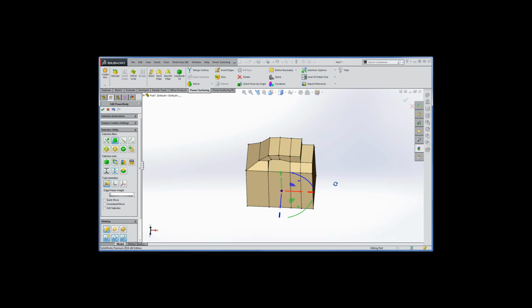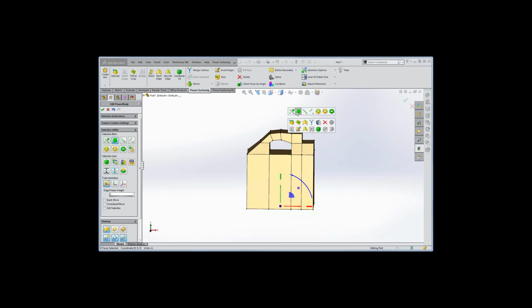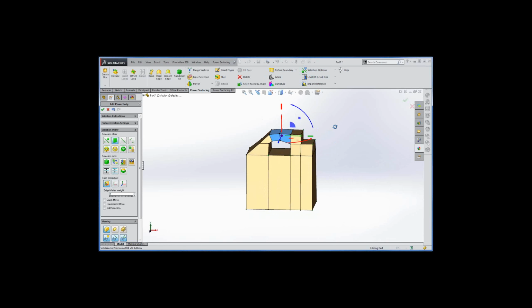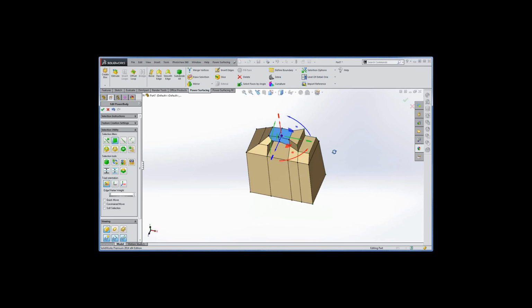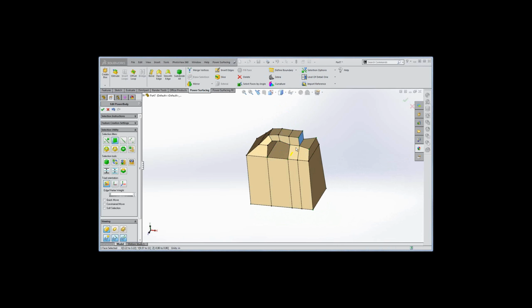And if we look at it from the top view, you can see that's a pretty hefty-looking handle. I know my hands won't get around it. So I'm going to double-click, just like we double-clicked to get a ring of edges. I'm going to double-click to get multiple faces. I'll double-click the other one here, and then I can just pull them in, make them a little easier for me to grip if I have to hold this gas can. All right, and I'll do the back end while I'm here as well.